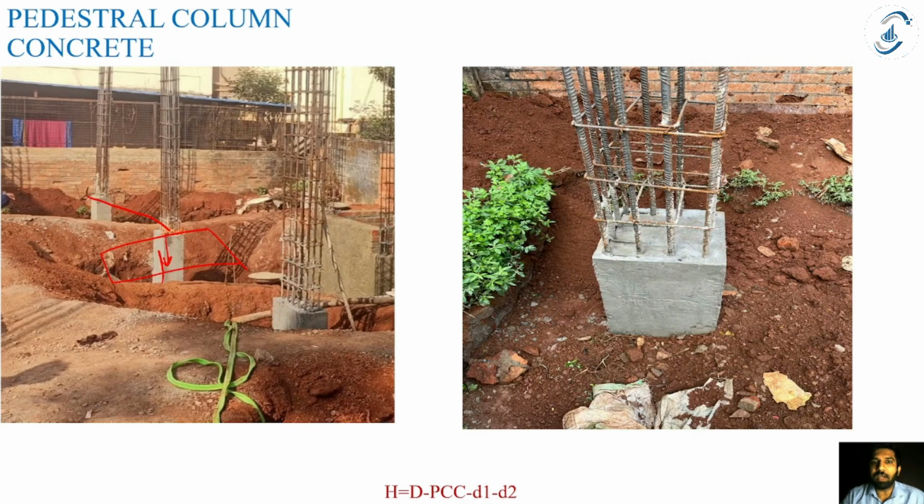So what are the details that we need to study from the column drawings? That is the length of my column, the width of my column, and the rebar details. We don't have the depth of column because it is going to span right from the foundation up to the last floor. So just the length, here you can see clearly, this is the length of my column, this is the width of my column, and these are the rebars, and these are my lateral ties. So these are my lateral ties here, and this is also my lateral tie here.